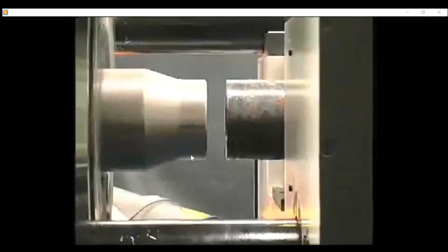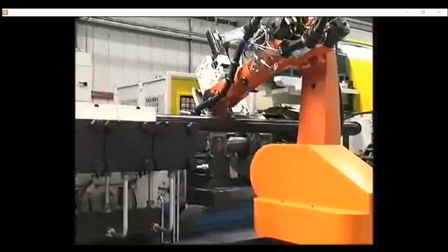Okay, here I stop the video. Here, this one is rotating, and this one is not rotating. We need to have a relative motion between these two parts, so friction will increase the temperature. The function of the friction is only to increase the temperature because we need to heat the material. We can do it without heat, we can just apply pressure and the weld is done, but it takes time. So the issue is we heat this material to encourage the atoms to move quickly, to not take time, to become shorter.